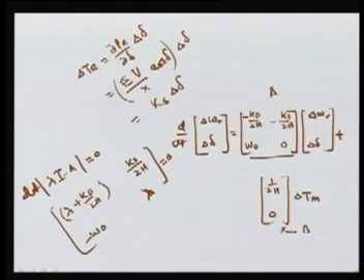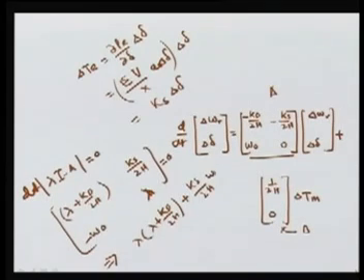Now we have to solve this, which means we can write the characteristic equation: lambda times lambda plus kd upon twice h, plus ks omega naught over 2h, equal to 0. You can see we are getting a quadratic equation.